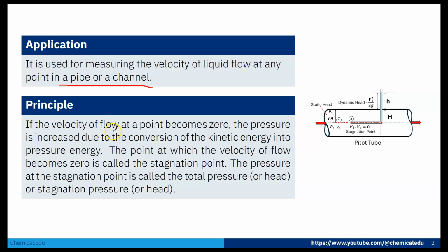If the velocity of the flow at a point becomes zero, the pressure is increased due to the conversion of kinetic energy into pressure energy. Based on this principle, we can calculate velocity. This is important. Based on that, we can easily calculate the velocity.